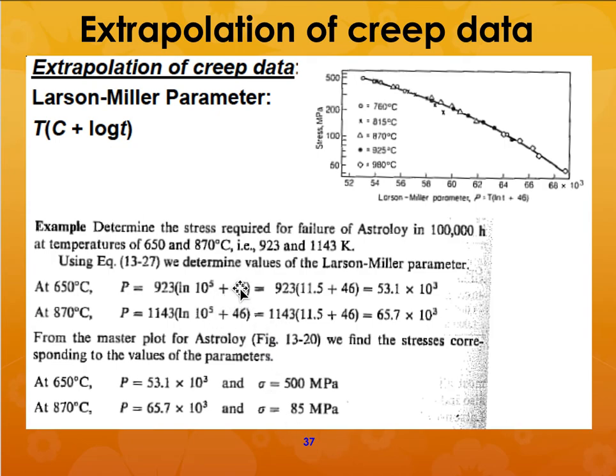Oh, okay. 10,000 hours is 10 to the power 5. Okay, 10,000 hours, 100,000 hours. So you want the component to last for 100,000 hours. And so if you increase the temperature, then you can only use this component at 85 megapascals or lesser. You got it? So you can actually calculate that, and this is just plugging in and calculating those numbers.